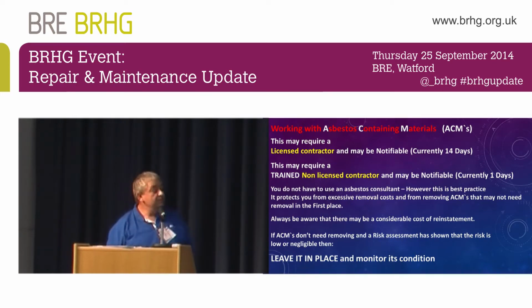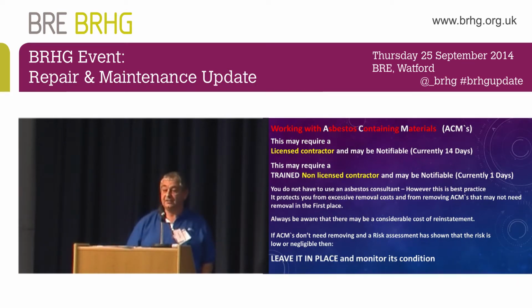You don't have to use an asbestos consultant. Don't have to do it. However, it is best practice. I could have saved people loads of money over the years. It protects you from excessive removal costs and from removing asbestos-containing materials that you may not need to remove in the first place. And of course, there's always the considerable cost of reinstating a really durable, fireproof material, because you're going to have to replace it with the same fire-rated material, normally, especially ceilings.